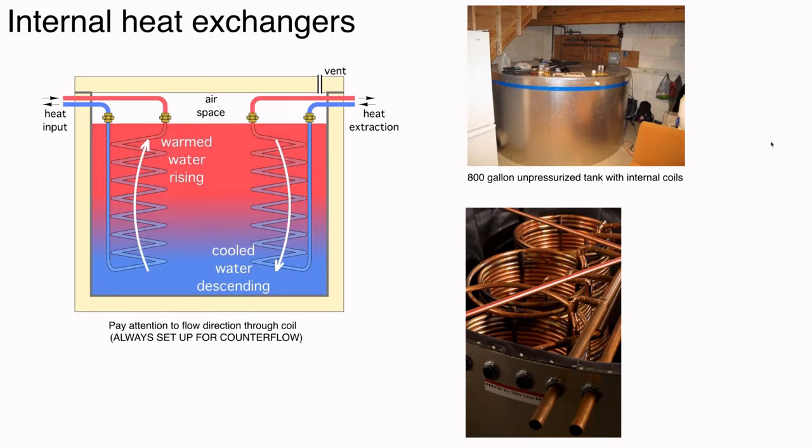And the common approach, actually for several decades, has been to use these large copper coil heat exchangers that are immersed in the water in the tank. You can see the connections down here in this photo. The connections are near the top of the tank. They're just above the water line. There is a seal there to minimize any evaporation from the tank, but those connections are actually not designed to be submerged. And that sets up some interesting pressure dynamics. I won't get into them, but it is possible to do this, certainly.